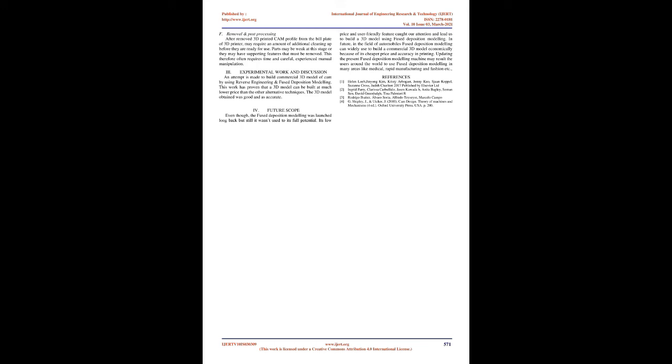3D printing setup. The 3D printer machine must be set up properly before the build process starts. These pre-process settings relate to the build parameters like the material constraints, power source, nozzle diameter, extruder velocities, temperature, setup of build plate, etc. 3D printing of cam profile. Building the physical component is mainly an automated process, and special supervision is required to ensure no errors have taken place, like running out of material, power, or software glitches, etc.